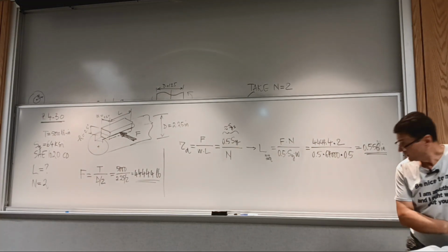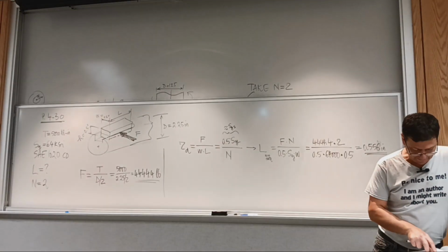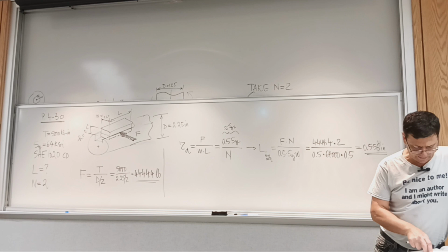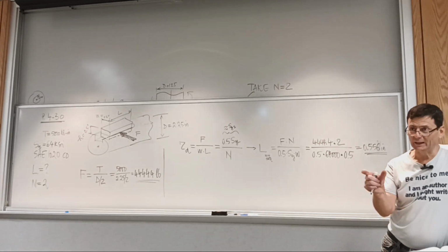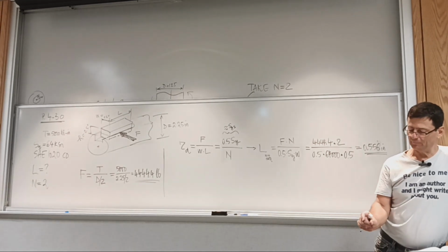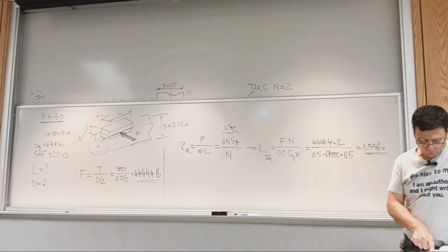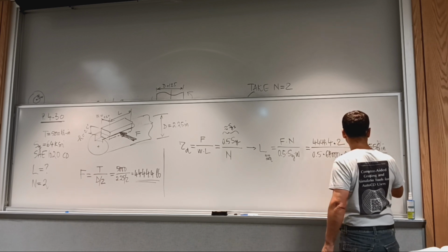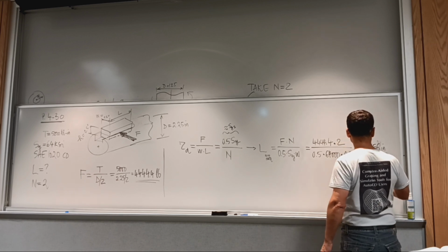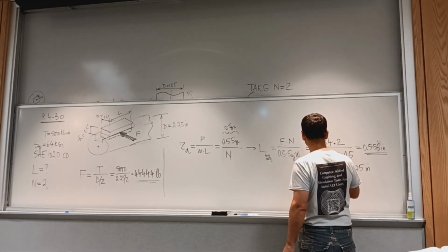Okay, so I was looking for the list of preferred sizes, and we have 0.5, and then it's 0.5625. I mean, we can take 3/4 to look a bit more like a long key, but even 3/4 might be too short. But let's go with 0.5625. 0.5625 inches, just because it's a preferred size. But again, it's too short a key.